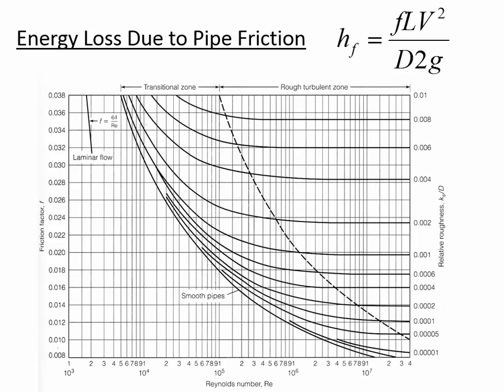First of all, on the horizontal axis, you can see it's saying the Reynolds number. And the Reynolds number is a dimensionless representation of the flow conditions. And one way of calculating it is the velocity times the diameter divided by the kinematic viscosity of the fluid. And from that expression, remember that when the Reynolds number is greater than 4,000, that tells you have turbulent flow. When it's less than 2,000, that means you have laminar conditions, and then in between is something we call a transition range.